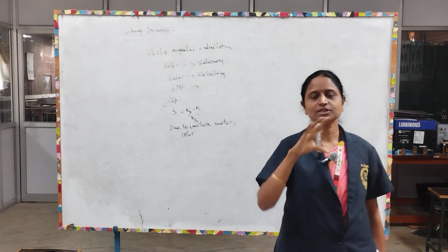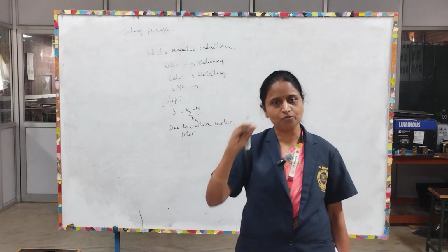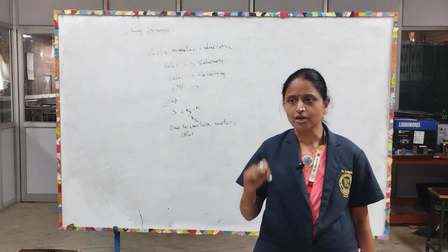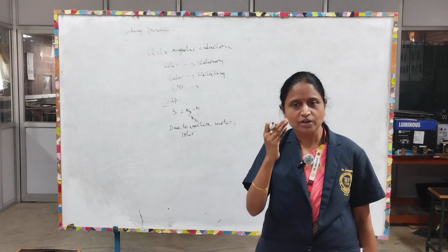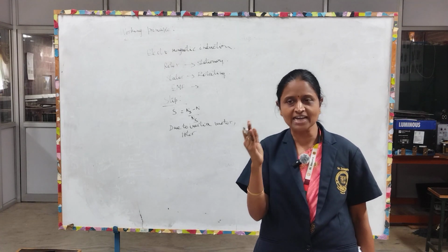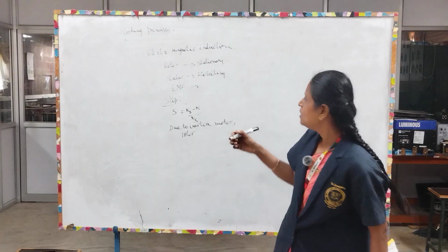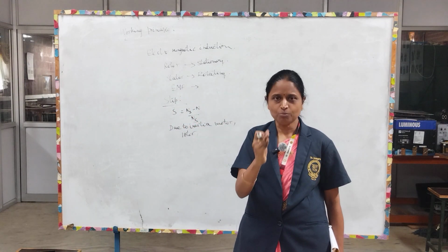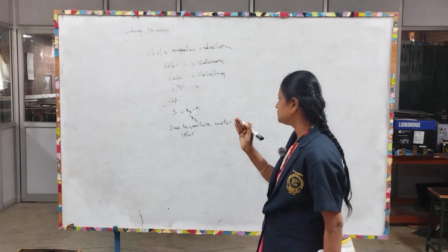Imagine you have a three-phase supply given to the stator of the induction motor. A rotating magnetic field of constant magnitude, revolving at some angle difference, is produced. So here we have a constant magnitude but its axis is rotating continuously.